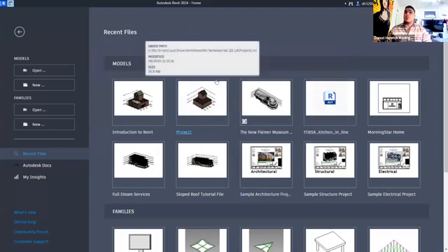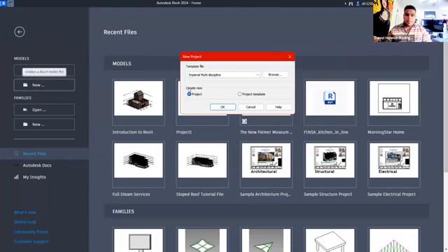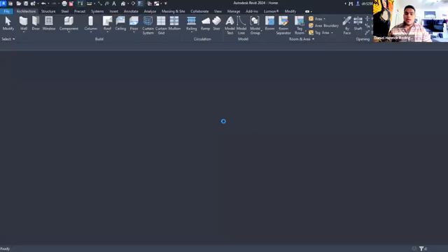Let's go straight into it. Let me share my screen here. We're going to be using Revit, so you're going to want to open Revit here. Once you have it open, we're going to click on New, and go ahead with the Imperial Multidiscipline. Don't have to change anything here. It's going to go with the project. These are just pre-made templates by Revit. We're going to hit OK.